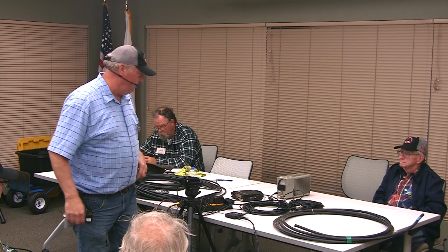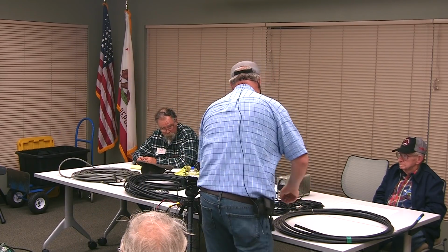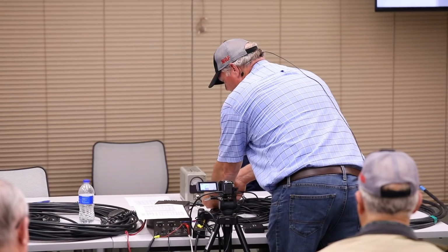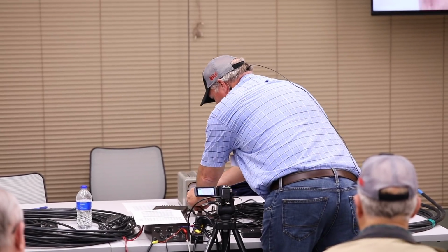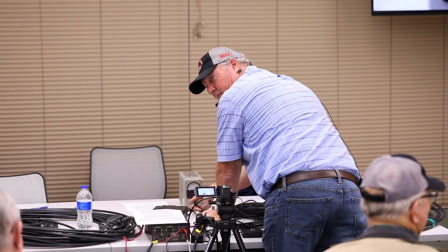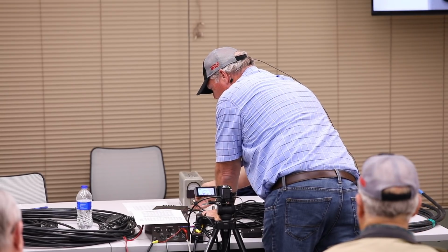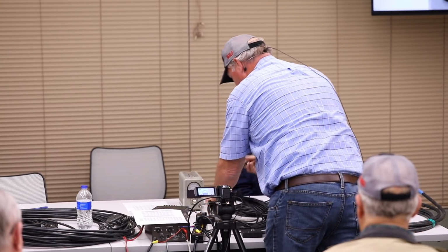So we did the most common cable just for fun, and we picked our 2 meter frequencies because that's what we use, and our 440. Let's disconnect this cheap coax. Or let's use the words cost-effective coax, because it has its place. I didn't even bring RG58 because, in my opinion, that stuff is so lossy for home and base station use. It's just for lower frequencies and or higher frequencies.